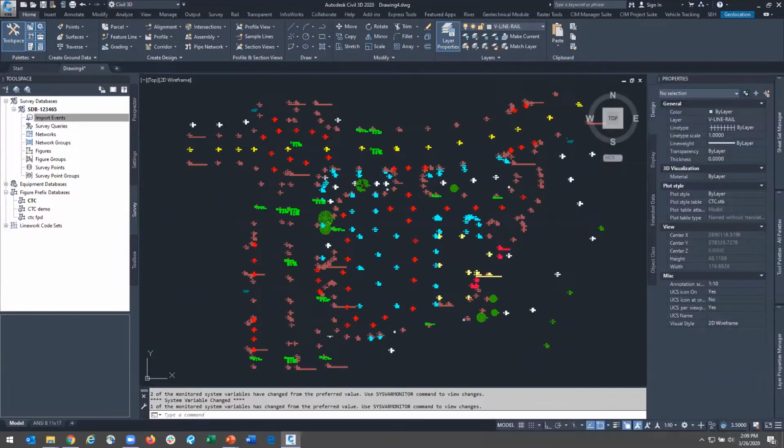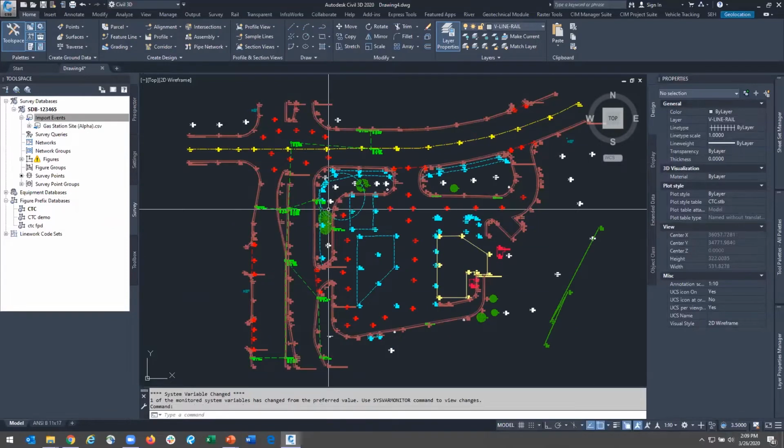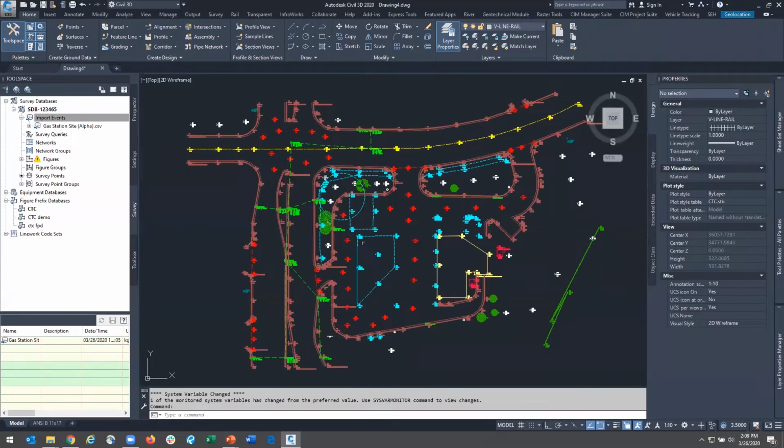I'm going to zoom to that part of my drawing. And now I've got all kinds of pretty colors and good blocks, and I've even got some of that line work. So this all came together because I have these settings put together between my survey template, my DWT file that I'm starting with, as well as some of these other survey settings that might live outside of my DWT, but we're still interested in taking a look at those.